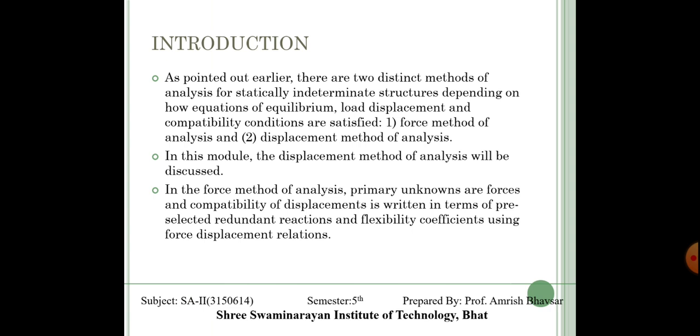In the force method of analysis, the primary unknowns are forces and compatibility of displacement is written in terms of pre-selected redundant reactions and flexibility coefficients using the force displacement relation. So, all of you are aware of the redundants and kinematic indeterminacy.